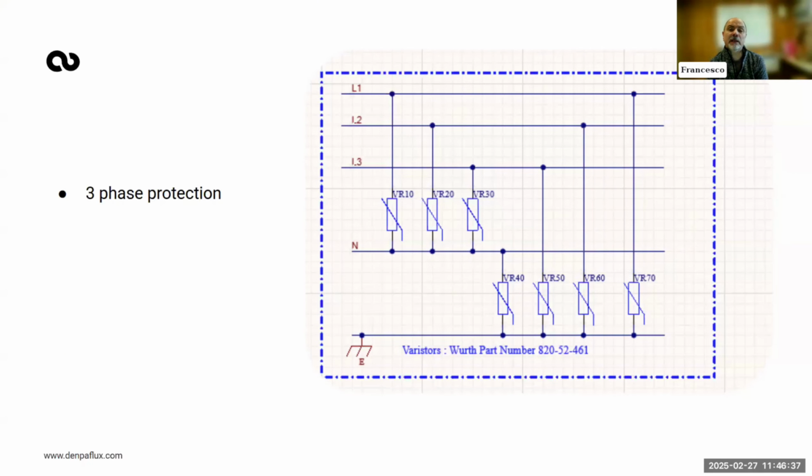When you have a two-phase or three-phase system, I usually use a varistor everywhere. Yes. And this is a typical solution that I use. This is another of my templates, pretty much. I use pretty much this template in most of my designs.